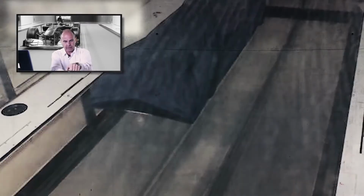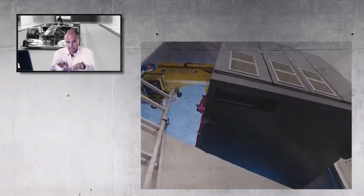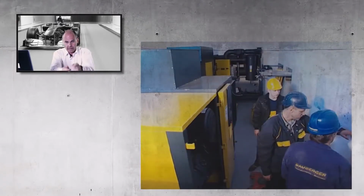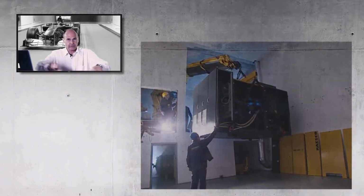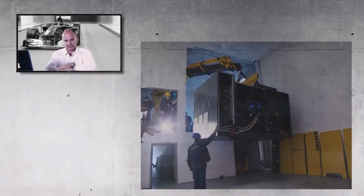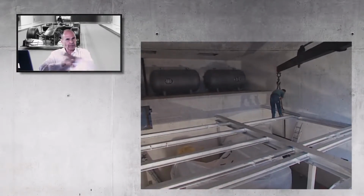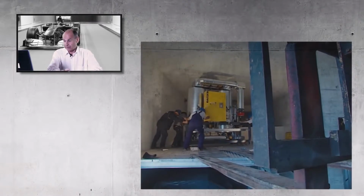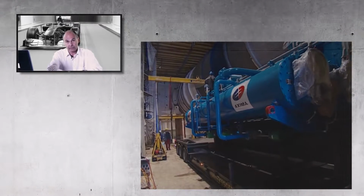So basically you have approximately 20 mil wide strips of air bearing, and either side you have vacuum lines. So we have rather large vacuum pumps within the wind tunnel building. Every 20 millimeters it sucks away the air that's being pumped in, so you have air being pumped in, air being pumped out. The interesting thing is that the horsepower you need to drive your belt reduces dramatically, because the belt is supported on air bearings, and it literally is floating on air.